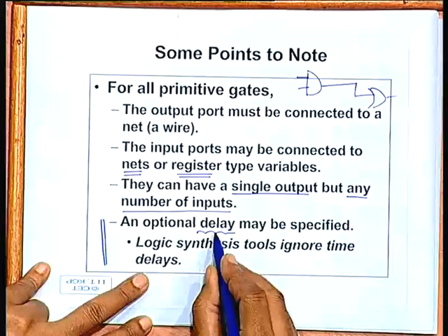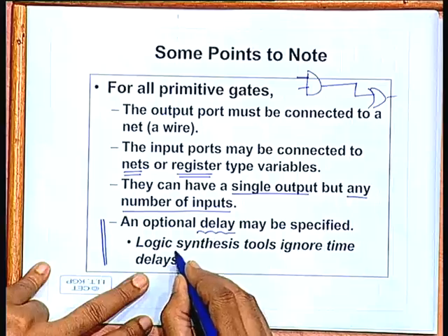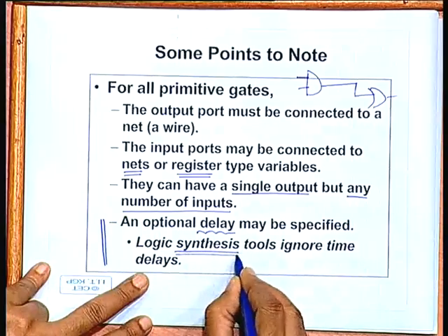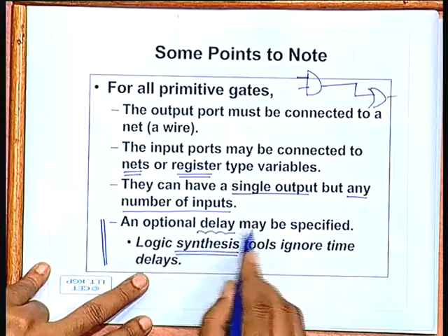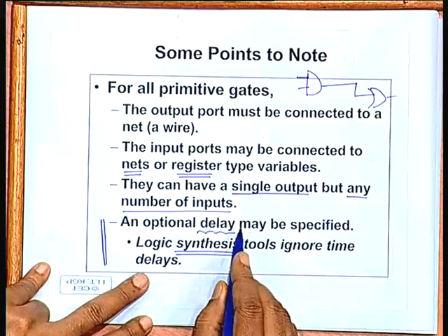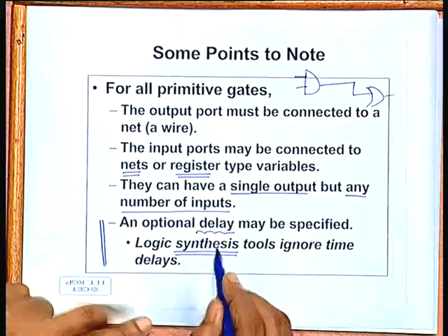This delay specification is used only for simulation, and when you are carrying out a synthesis, synthesis simply ignores those delay specification commands, because synthesis is carried out by a software tool which will be targeting some target libraries which are already there. Now, the libraries contain some gates or other components whose delays are already known, pre-specified. So, the user cannot give the delay.